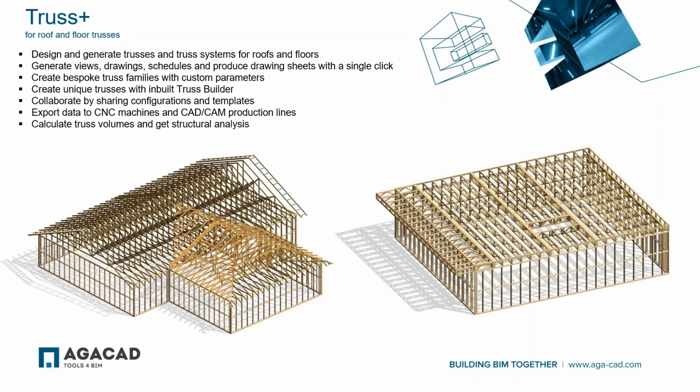Okay, and the other way is if you are using trusses as your primary structural framing elements, we can use Truss Plus, which comes together with Roof Plus within the package. We can design and generate trusses and truss systems for roofs and floors as well. We can generate views, drawings, and schedules like I mentioned before. We can create bespoke truss families with custom parameters. We can create unique trusses with the inbuilt truss builder. I'm not going to show truss builder in this webinar, but we have covered this in past webinars. If you go to our YouTube page, you can find this video, so you can have a look at that.